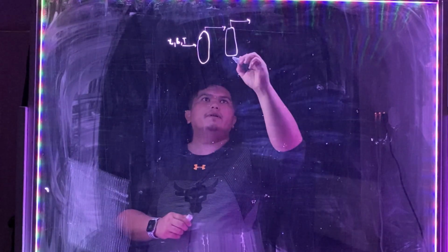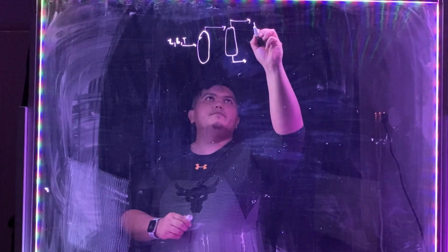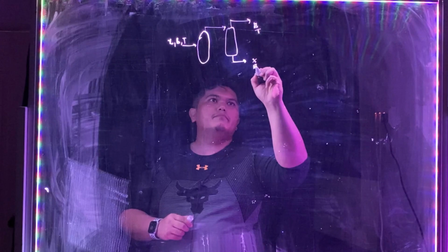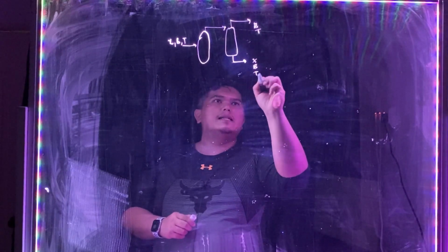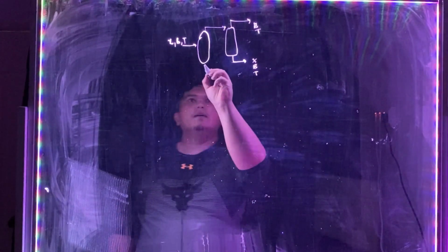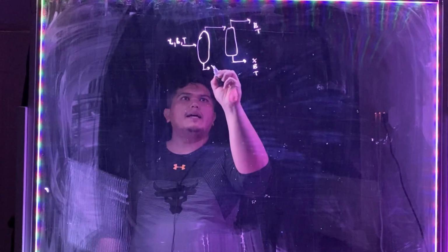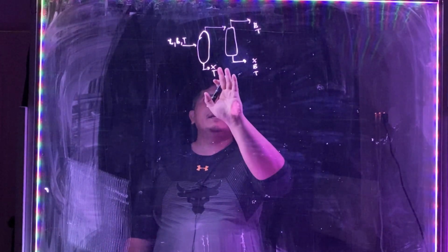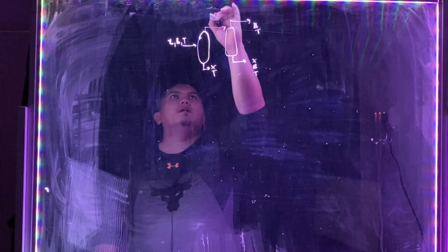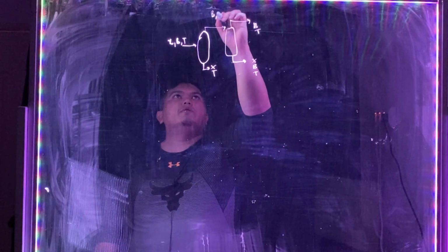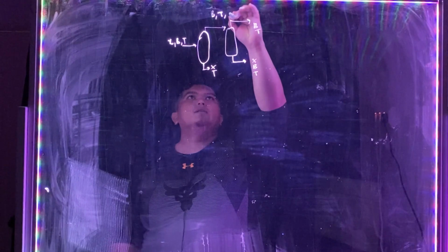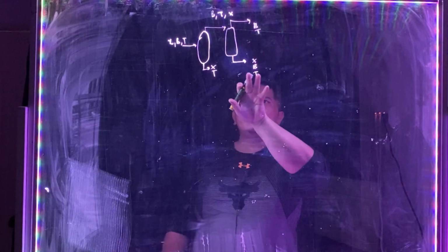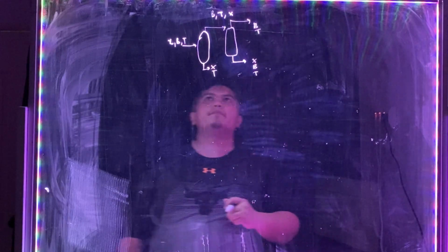Then you will have another product, which is benzene at the top with toluene, and then you have xylene, benzene, and toluene at the bottom, which is largely toluene. In the first column, you're going to have xylene as well as toluene. There is no benzene here. Benzene will go to the top, together with toluene and a trace amount of xylene, which will be separated in the second column.